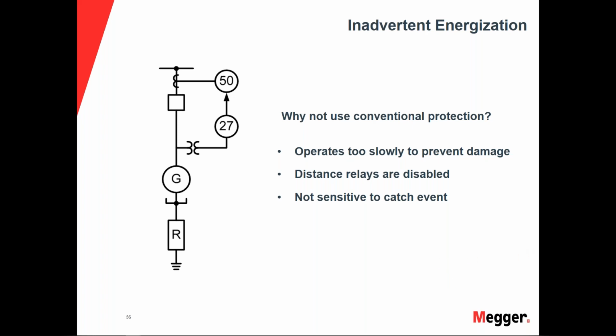It seems to be a big industry-wide problem that it warranted its own protection scheme, and has been set in the IEEE standards as well, that we actually need to protect against a standstill generation. We're using a combination of an overcurrent and an undervoltage relay to sense this type of issue. So the ways that this can actually happen is, well, I just told you how it's going to happen.